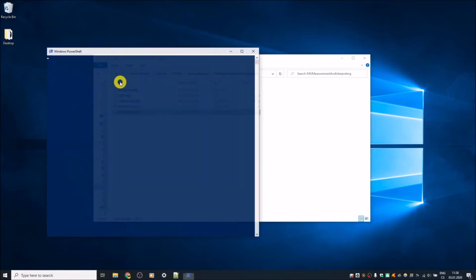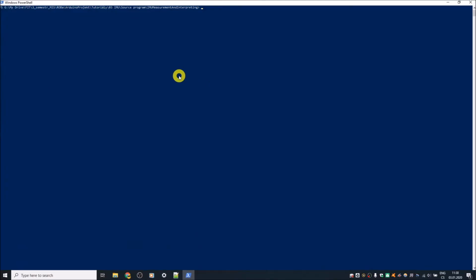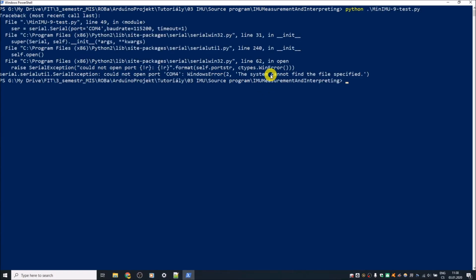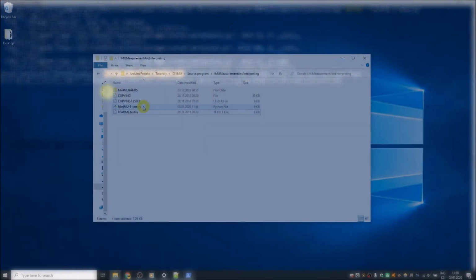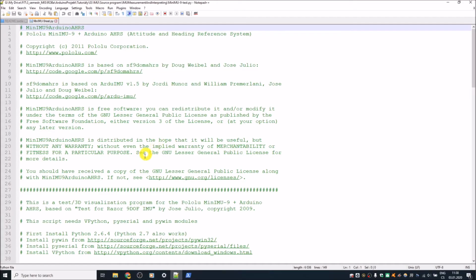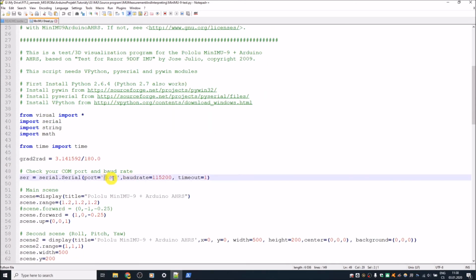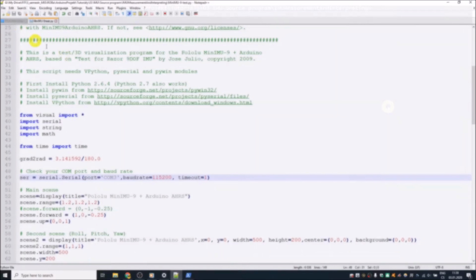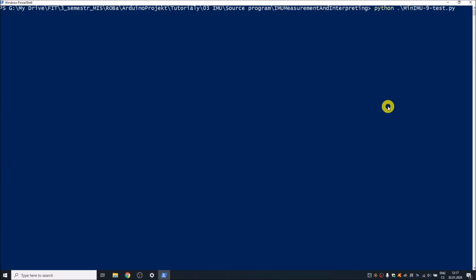I'm going to run the script. Oops, error. It's because my Arduino board has to be connected before running the script. And the correct COM port has to be set in the Python script. If you don't know about COM ports, look at the first video of this series. Let's run the script again.